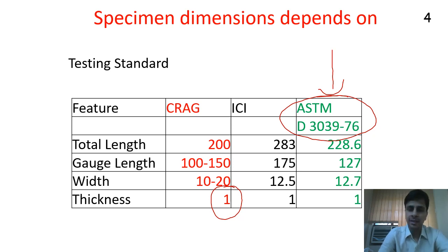And since, given the current situation, maybe we will not get to do the test, the next best thing is to at least read the test standard. Very detailed and precise instructions are given on how to prepare the sample, how to cut it, what should be the length range, what should be the gauge length range, and so on and so forth.